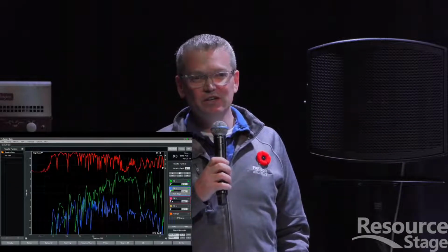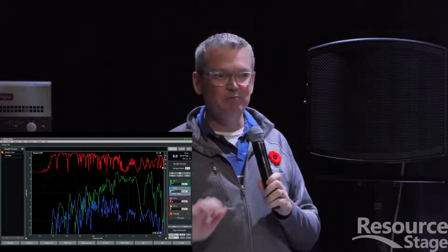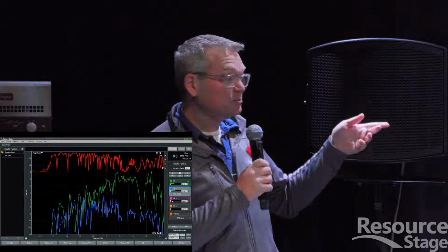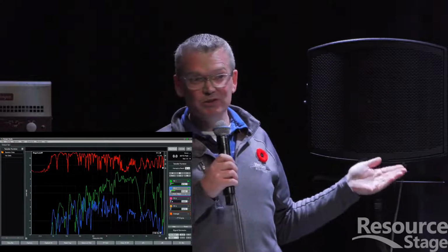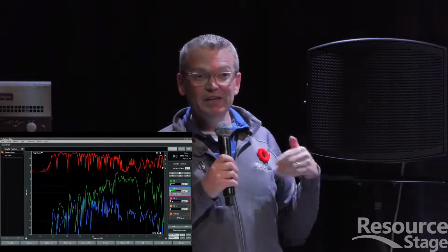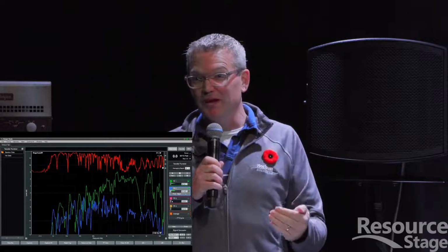And little things like that can destroy sound systems really quick, because, as Paul was just pointing out, we're seeing on Smaart how it's cutting out that low frequency. Well, if you're thinking, wait a minute, where's all my low frequency? You just keep pushing it. Well, the speakers are still producing that sound. We're not hearing it with our ears. The microphone is not picking it up, but that sound is still being produced by the speaker. And so if we keep pushing, you can blow up that driver.